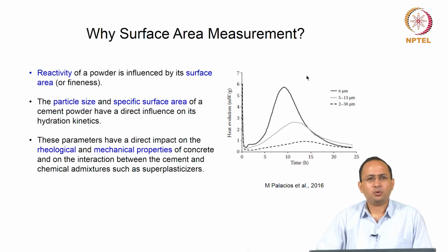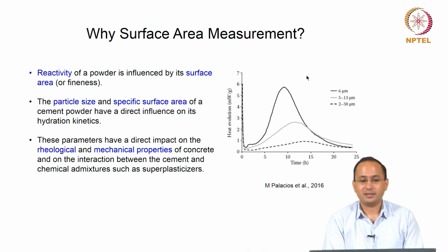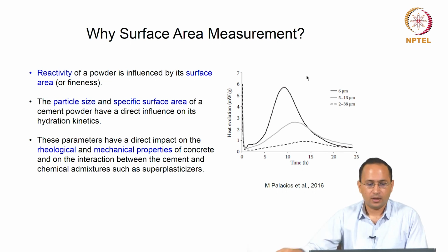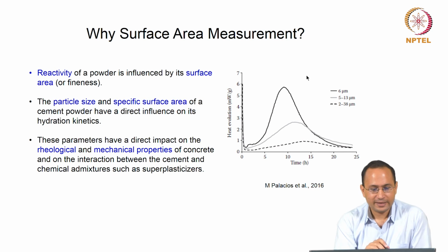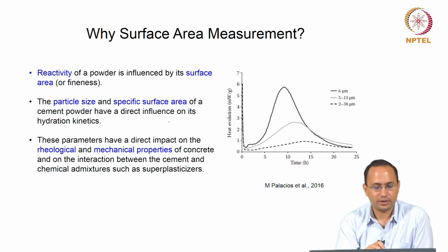So why do we need to care about surface area measurements? The reactivity of a powder is influenced by its surface area or fineness, right. The particle size and specific surface area of a cement powder have a direct influence on its property, hydration kinetics.